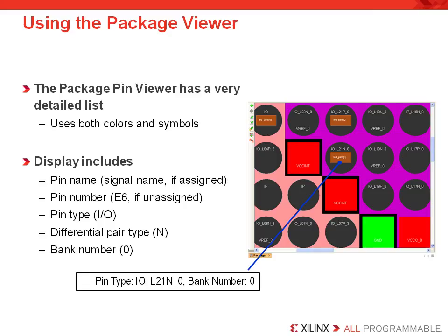The power and ground pins are reserved and given a square with either a red or green color. You should also note from this example that VREF, or the reference voltage pins, serve as a dual-purpose pin with the I/O pins. This is easily seen by reading the text at the bottom of each pin's circle.